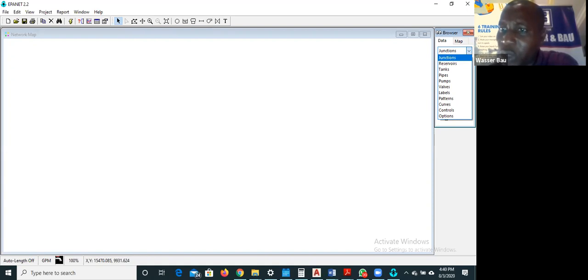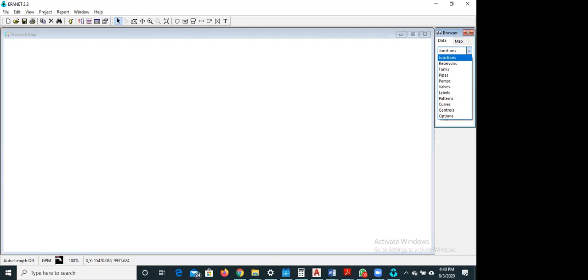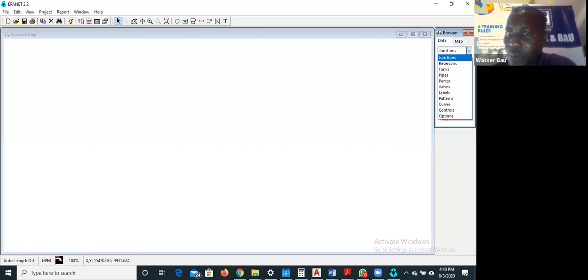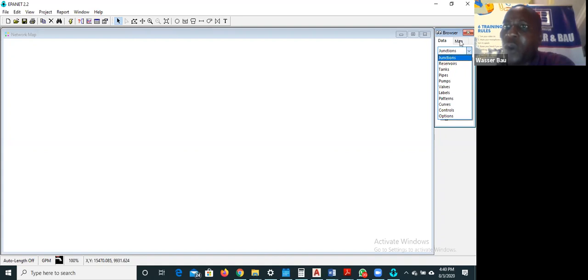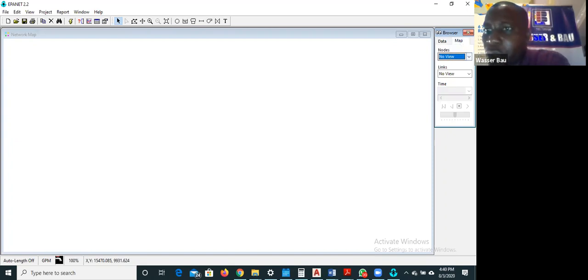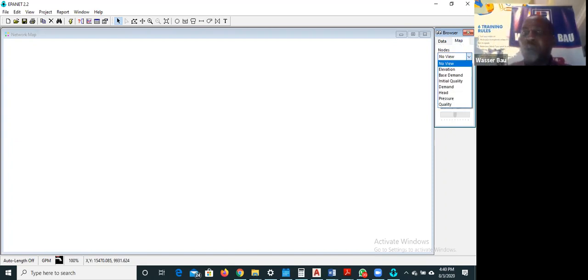You have your junctions, your reservoirs, your tanks, your pipes, your pumps, your valves, and so on and so forth. And when it's time for results, if you want to view your results, you simply go to map. When you get to map view, it will ask you what you want to view. What parameter do you want to view?